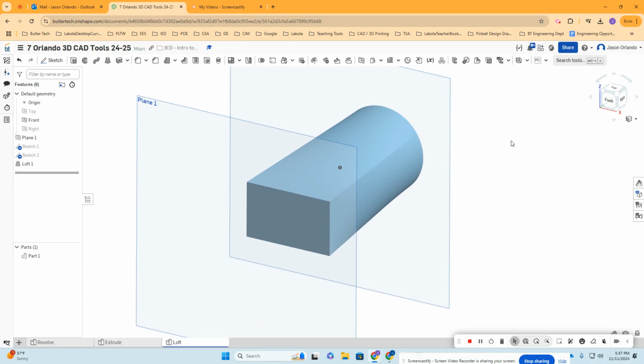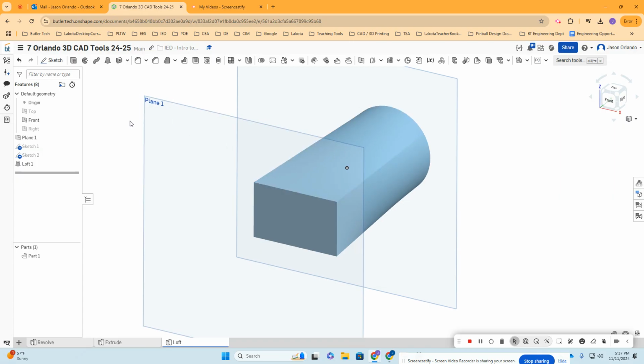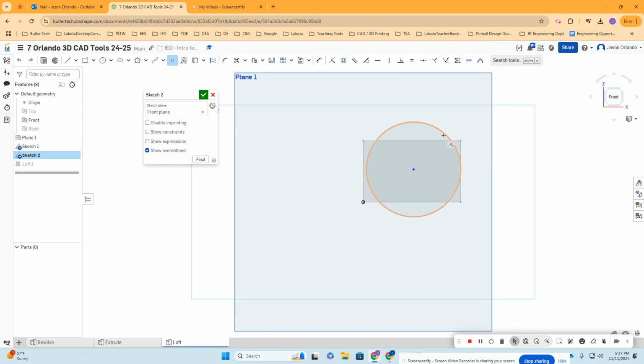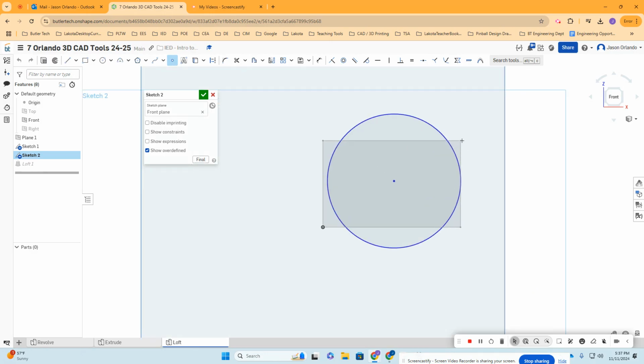So, how does Onshape really know where to kind of map that crease? Or can you control that? And the answer is you have some control. What I need to do is go into my sketch where there's the circle, realize there are no vertices whatsoever, and I'm going to make a point. Now, I'm going to put a point on the circle that doesn't map as intuitively from where a vertex of the rectangle is. It would make sense to put a point somewhere here. That's kind of where Onshape's naturally going to aim at that point. And I'm going to put it up here.